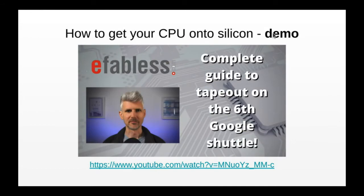If you do want to do that, I put together a video working with EFabless recently, which is a half-hour video that covers all the steps you need, from installing the tool chain to building a demo project and then submitting it. You can watch that on this link here. And what I'm going to do now is a demonstration to show you what it looks like as you go through the hardening process, where you take your hardware description language and turn it into the files we need to send to the foundry.